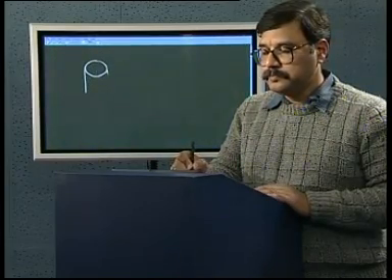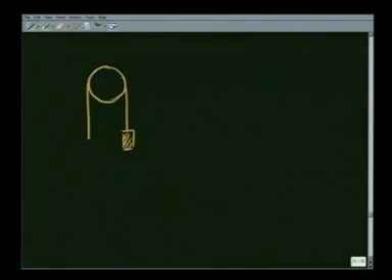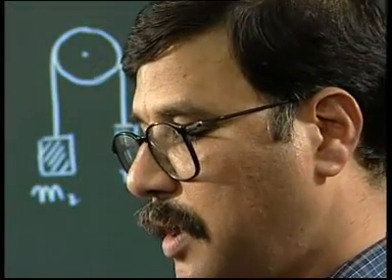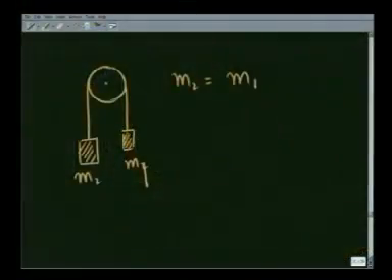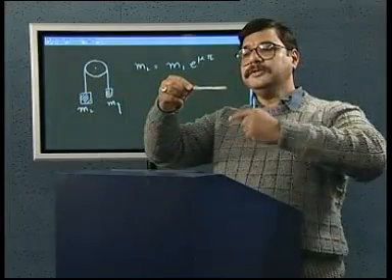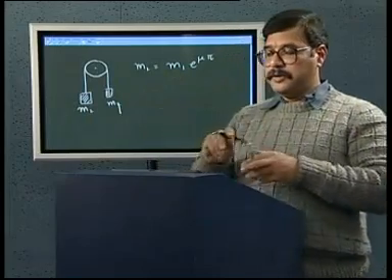How do I do that? You take a pen and put a small object, maybe a pin or a key, on one side, and a large object on the other side of a string, and try to balance it. As we said earlier, suppose this mass is heavier, m2 would in this case be equal to m1 e raised to mu pi. So, I will take this pen, wrap a string around it once, and this relationship would be satisfied. Let me give it one more wrap.